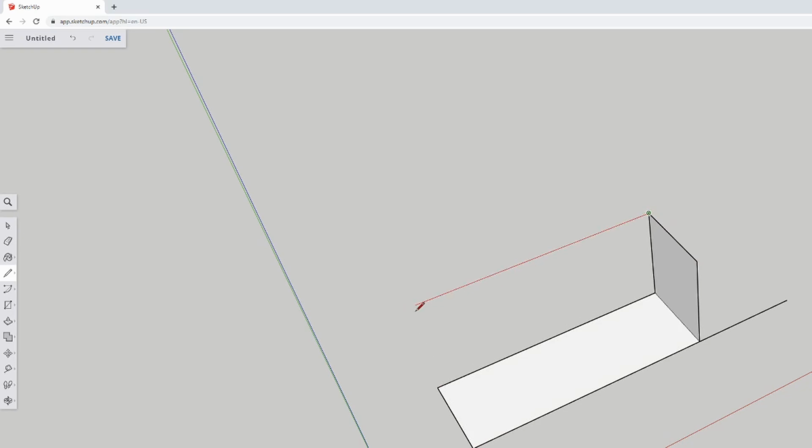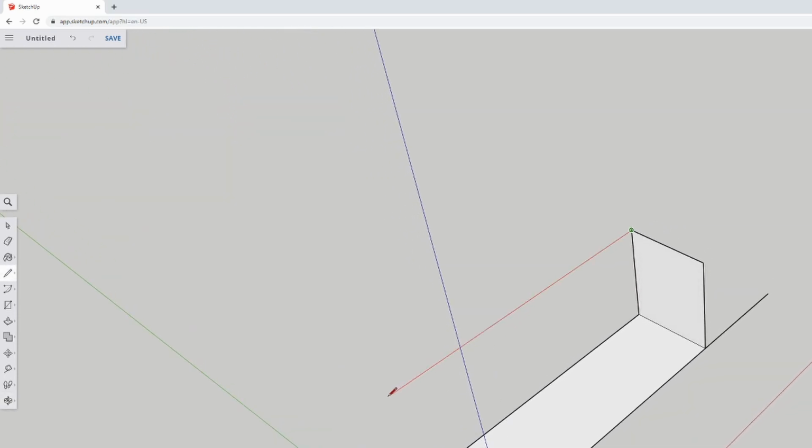Now there are a variety of different ways that you can create these types of lines. In this case, you'll see this is kind of tricky because it wants to snap to the closer end point. But if I did that, it would actually cross the piece and it wouldn't form a proper rectangle. So while I'm still on the red axis, sometimes you can trick it into selecting the correct one. Obviously you can rotate the piece in order to identify the correct point.